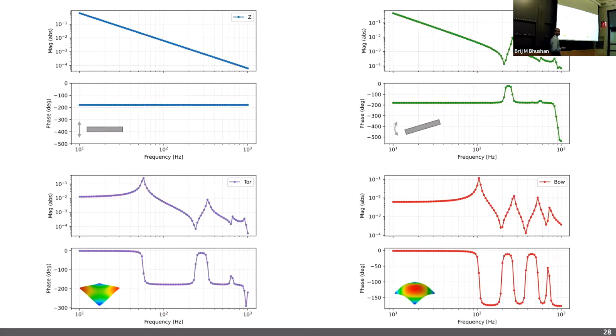So interestingly, when we combine all of them together, in the z direction, all the modes disappear because of the symmetry of how we are placing the sensors. We have no modes that show up. And why is this important? Because especially in the z direction, as the air gap reduces, due to the increasing negative stiffness, I have to achieve a high crossover frequency.